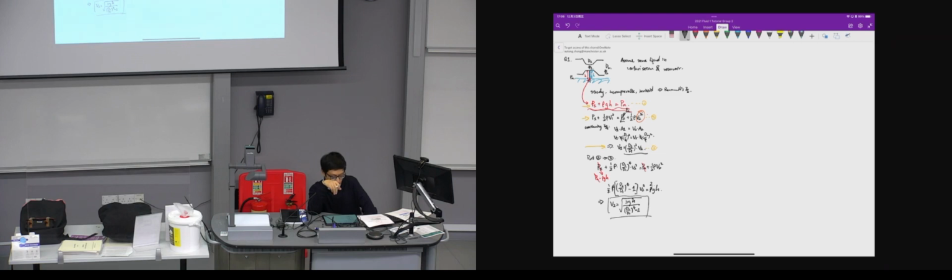As in the static pressures. Exactly. P1 is equal to PA plus rho g h, and P2 is equal to PA. Okay, so we take P1 and P2, insert them into the Bernoulli equation. Assume that all densities are the same, and use the V1A1 equation, and that's it.